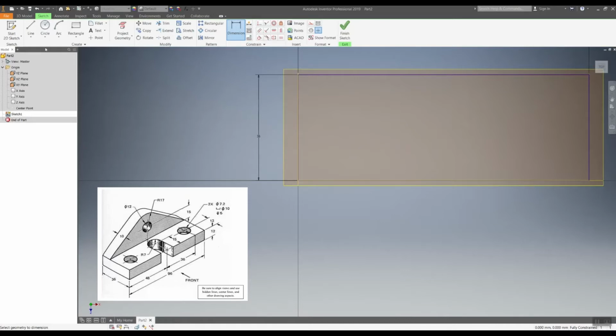So as you can see, this is what it started looking like looking down. Now if you see, it says 48 over. In the middle, there's this little cutout. 48 is the halfway point of 96. I can use my midway indicator to figure this out. If I just drag my little cursor along, you'll see it turns green. Well, that is my midpoint. If I go up 15, that's going to take me to my circle center or origin. It is giving me one radius here. That is a radius of 7.